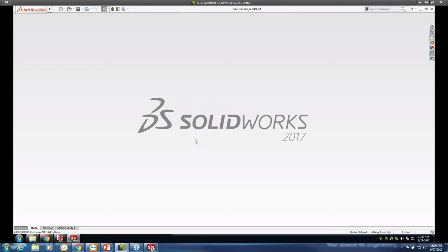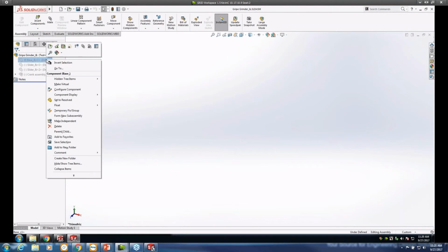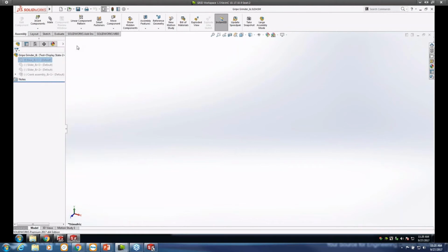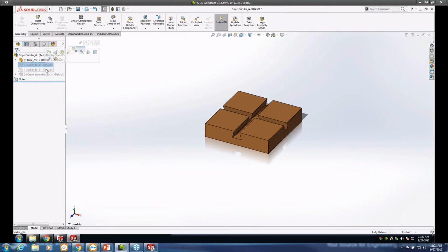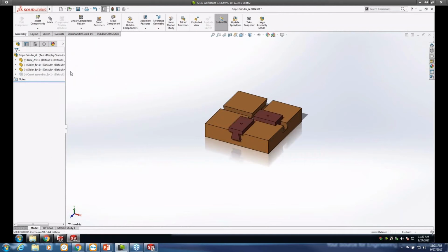However, if you click OK and the assembly opens up, fine. It's likely that there's an issue with one of the components of that assembly here. So you'll notice everything comes in suppressed. So to narrow down which component is causing the issue here, go ahead and right click on your component and unsuppress it, going through that one at a time. If you have multiple components, you can highlight them all and do the unsuppress here. And you just go through until you encounter an issue that brings up that error message or causes SOLIDWORKS to crash.